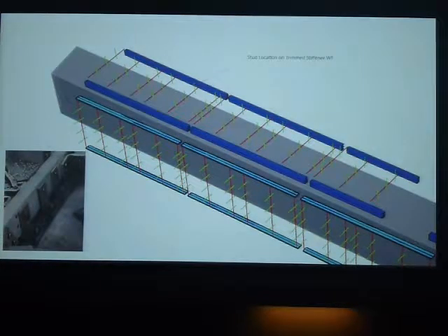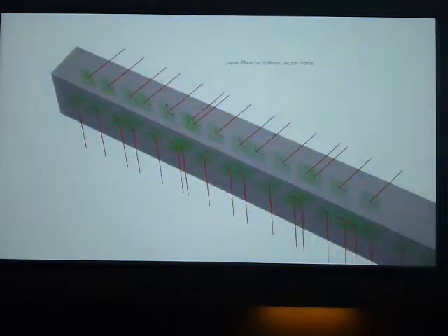The stiffeners need to be mechanically fastened to the panel surface, and this is done by means of welded studs. The stud locations are defined in this stage and are represented by these green lines. A section profile needs to be oriented normal to the wireframe curve and panel surface. And whichever section profile is needed is also, again, stored as an attribute inside this wire. So Grasshopper already knows which section to take for each wire.